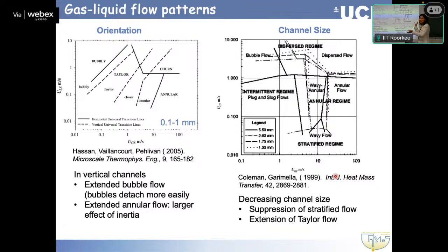I would say flow pattern maps, pressure drop in two-phase flows is like a holy grail. A lot of people do experiments. This applies also to large-scale flows if people come from this background. They try to put their observations in a map, and this is true for this particular system, either tube size, material, fluid properties, even inlet conditions. And of course, what we all want is to have a generalized way to predict the flow pattern transitions.